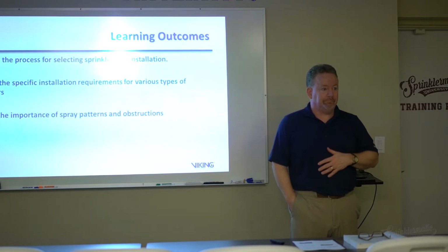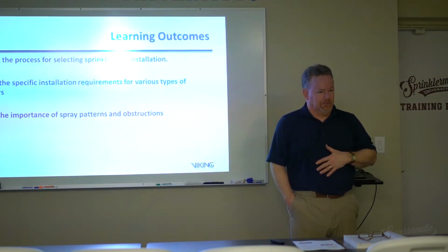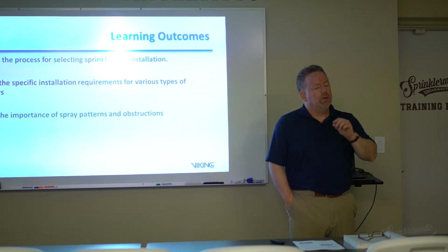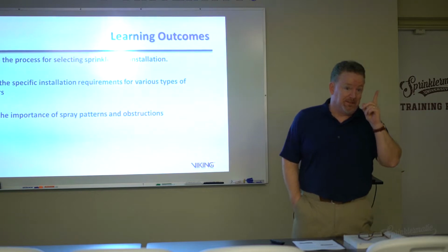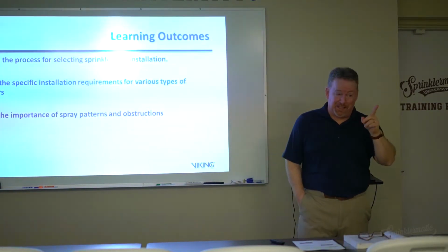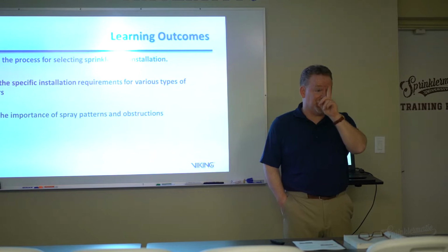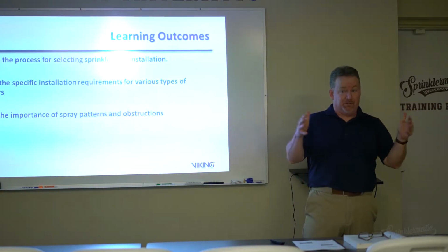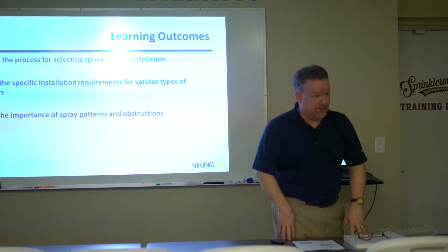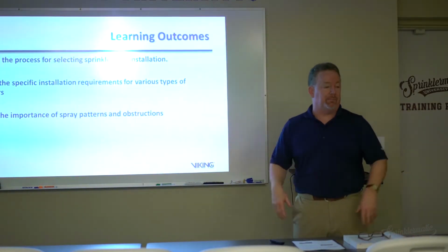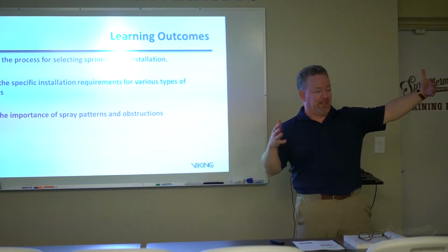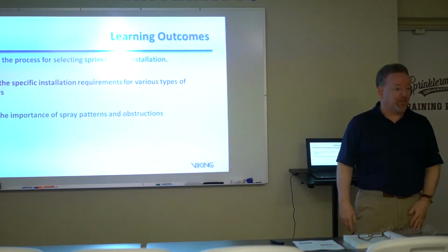So you obviously would have, your water supply would probably be your biggest restriction on the whole system, because they're not going to put a larger main or anything like that if they don't need to. You would need to evaluate a couple of things. It's not just the water supply, because it's also spacing. Hazard classification, increasing the hazard classification also may impact the restrictions on the area of operation. May limit you to say 130 square feet if it's a standard sprinkler, whereas with light hazard you can go up greater than that.